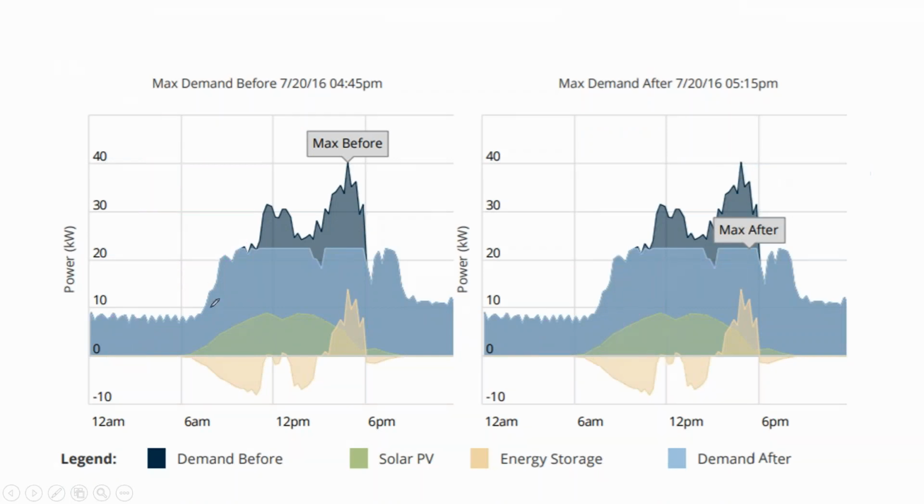and now it looks like what you'd imagine, it's both the solar array and the battery working together during the day. And then whenever your demand is below your maximum demand, the solar array is charging the battery so that it can be used when your maximum demand is hit. You're actually hard programming the inverters to say whenever your power draw, remember, your voltage is fixed.